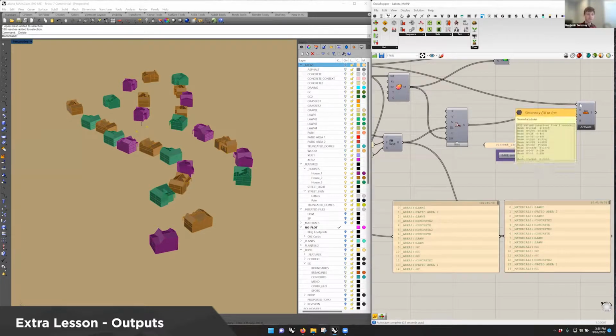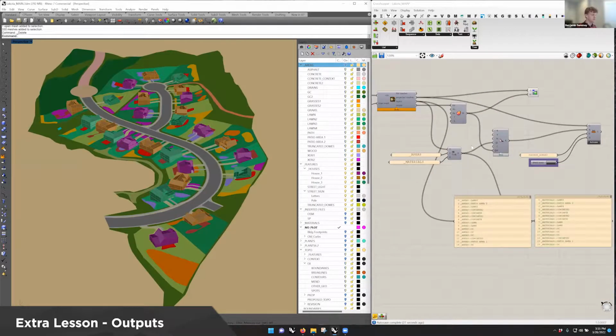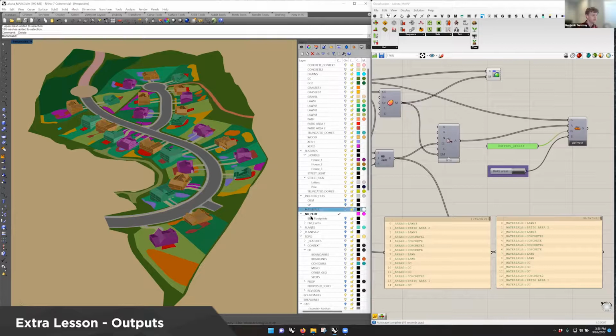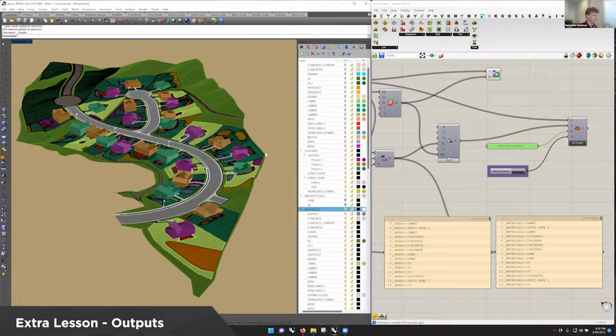So we have all of our meshes coming in from our project areas. All of these are coming in, and then all of our Elefront attributes, which are directly related to each mesh, are coming in. And then we're defining a name for the bake. So we're saying we want this bake name to generally be called whatever, current areas 3 is what we're calling it. And then we have a toggle that allows us to click this button and bake all that geometry straight into the materials layer. So now all of our materials are in here.